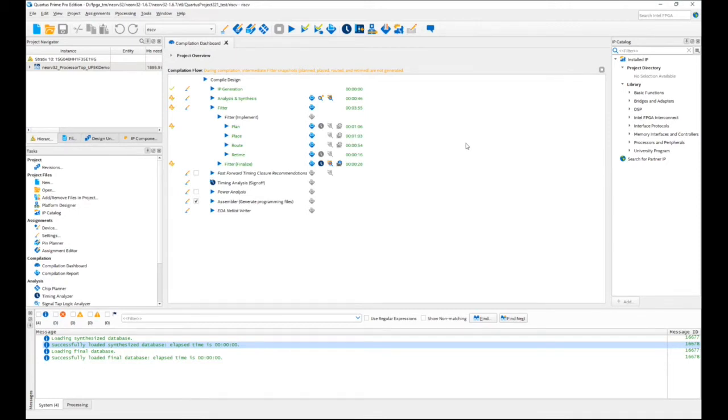Let's see. So differences also would be the gate count. The Agilex and Stratix are going to be the highest density chips. Lowest density chips would be the Max 10 part. Max 10 traditionally has been called CPLDs, but if you open up and look at the architecture of the latest iterations of the Max 10, it's essentially FPGAs where you've got your standard flip-flop lookup table combinations.